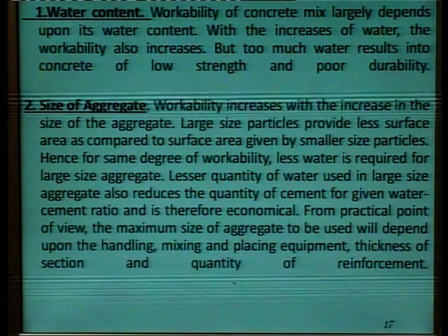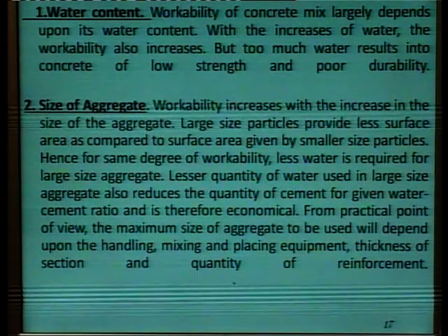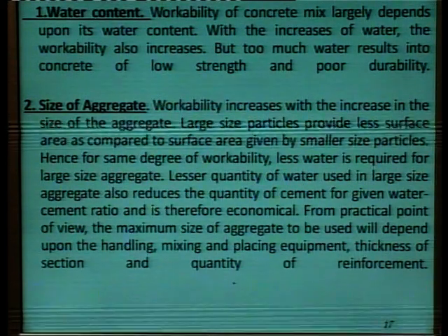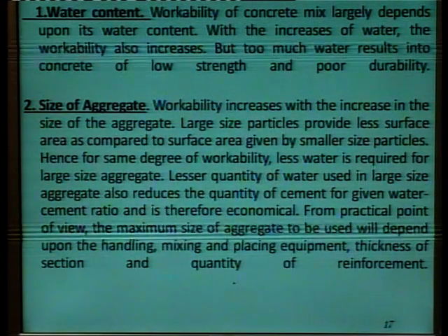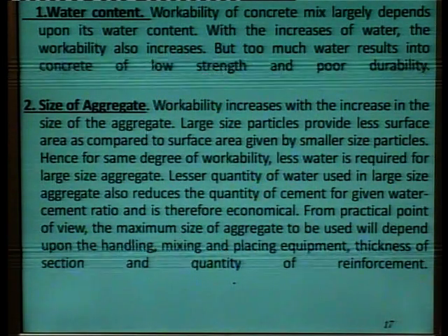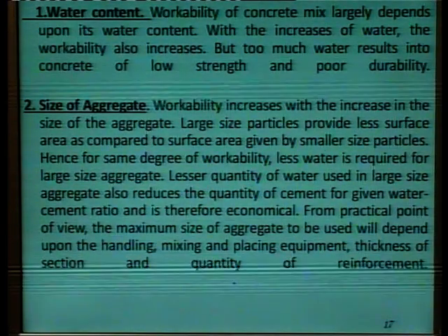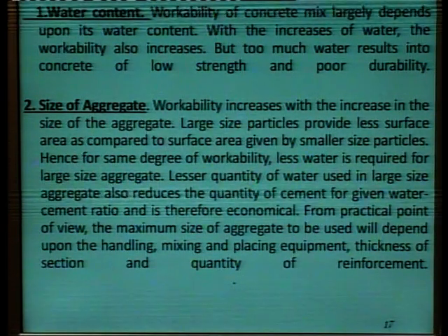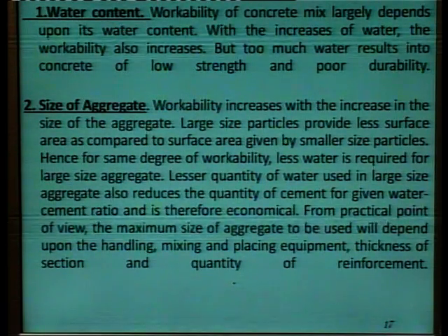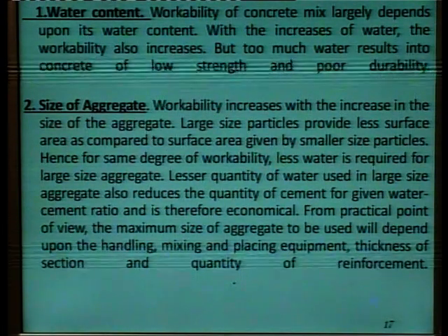Hence, for the same degree of workability, less water is required for large size aggregates. Lesser quantity of water used in large size aggregate also reduces the quantity of cement for a given water cement ratio and is therefore economical.